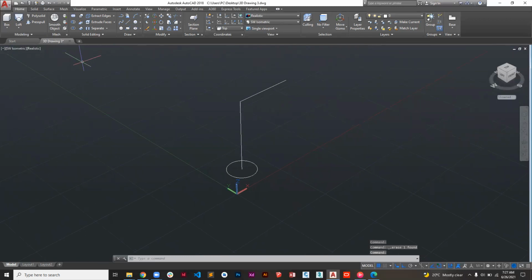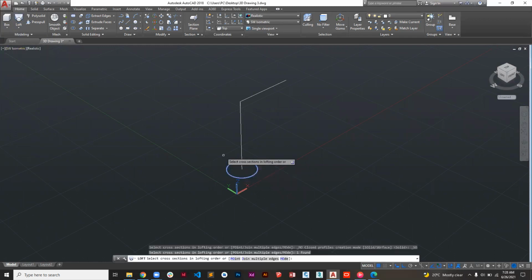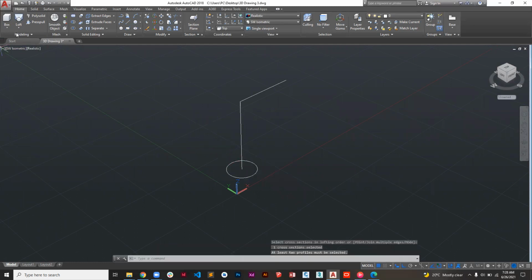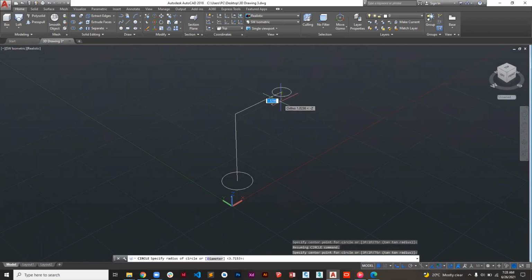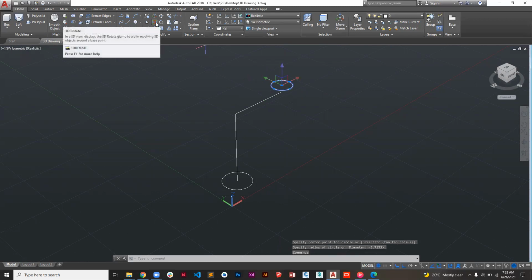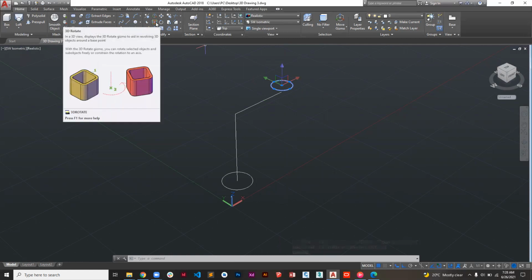You remember the other time when we were using sweep? Yes. So also Loft can do that, but when you select a path. So let me first try this. This is an object. Missing one object. I draw another circle, but here. Okay, here I want to rotate it so that it is on the other axis.